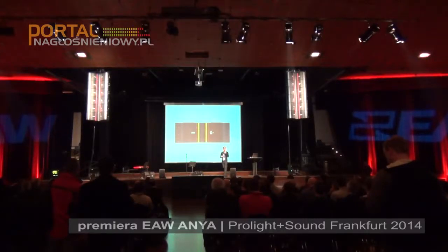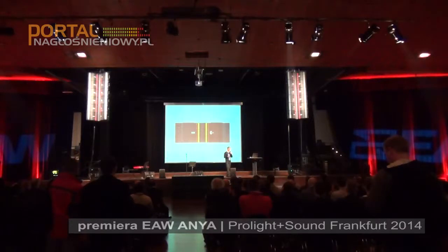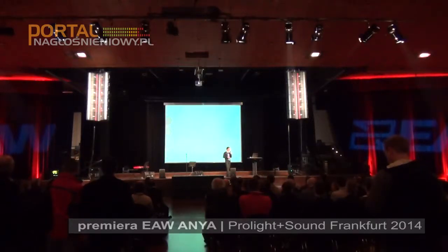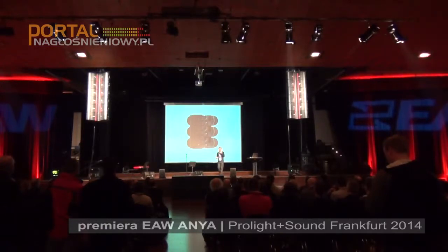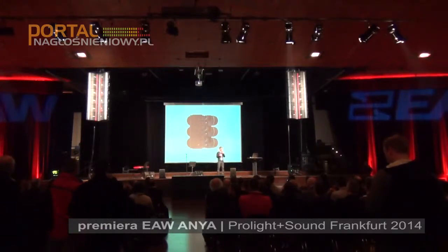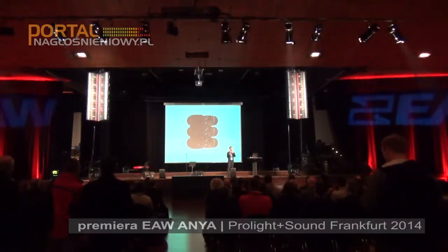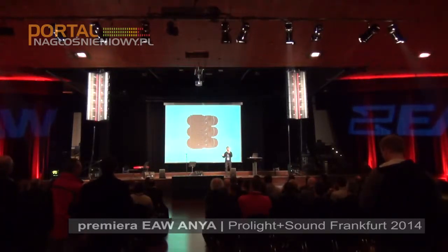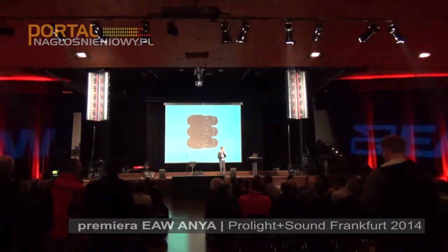This requirement allowed us to employ 2 proven and patented EAW technologies. The first is the radial phase plug. It was introduced many years ago in the KF750 system. The radial phase plug improves the time coherency of the mid-frequency wavefront itself, while also improving the impedance loading of the mid-frequency cone to that high-frequency horn.